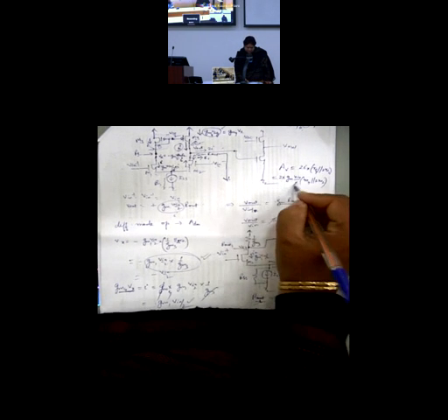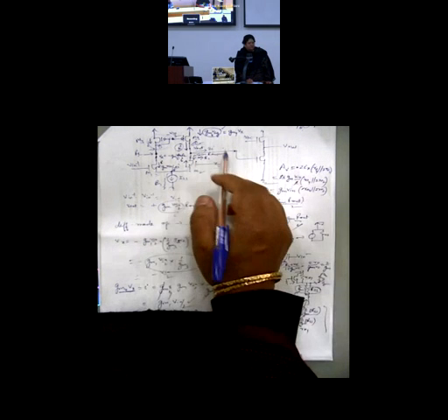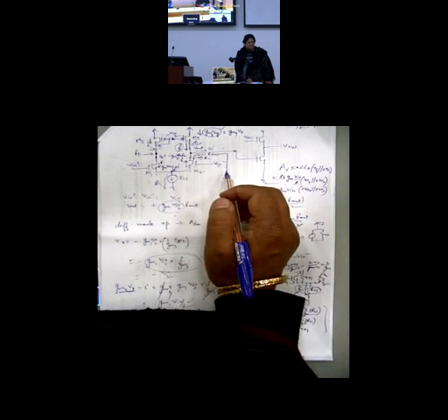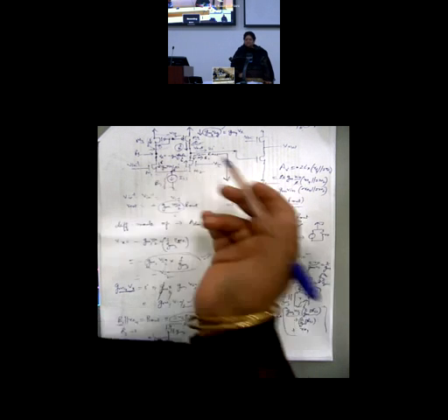Okay, so this cancels out. You get a gain of GM Vin approximately, times RO or whatever value you get for RO2. I will put a negative sign or a positive sign depending on which way current is flowing. If the current is flowing out, it would be a positive polarity. If the direction is opposite, it would be a negative polarity. Here it would be a positive polarity.